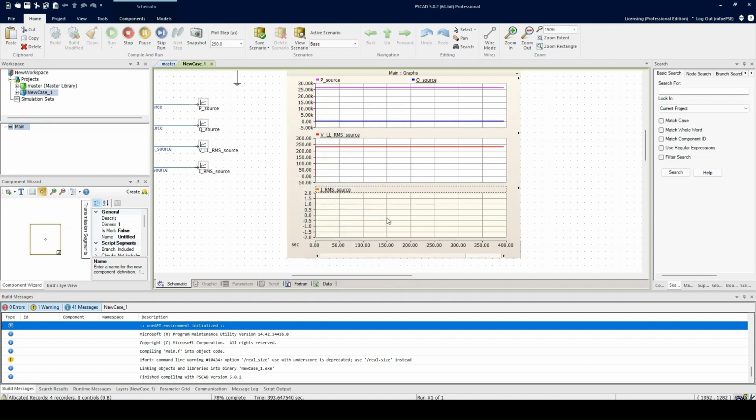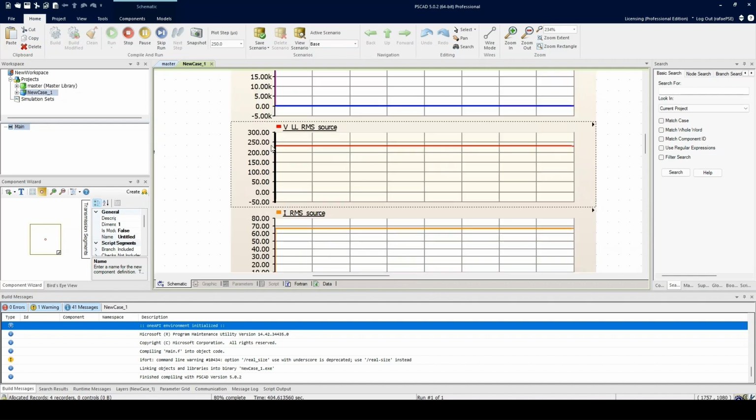Okay, so are we now getting the information? So I'm going to zoom in, click on this middle, click C, and that brings me this crosshair marker, and you can see right here all across is 230. So you can see the right side value, which is your Y value. It's 230 kV.